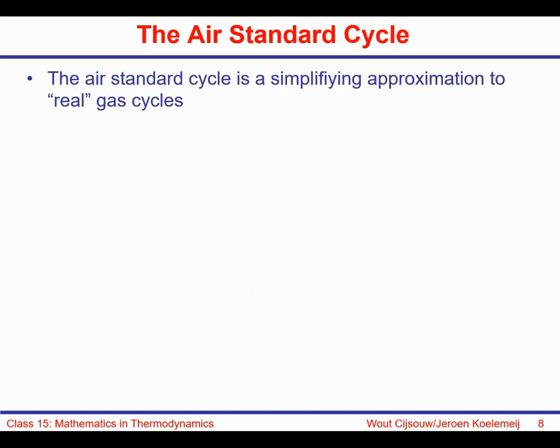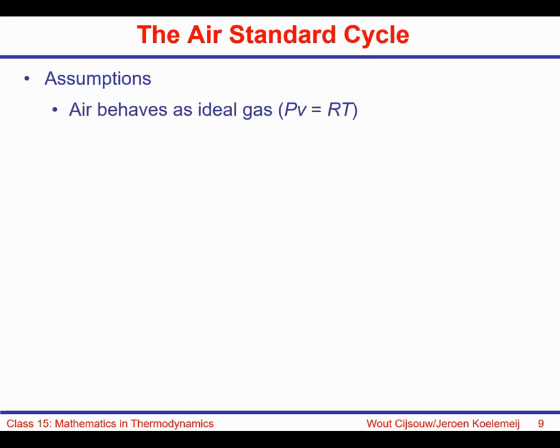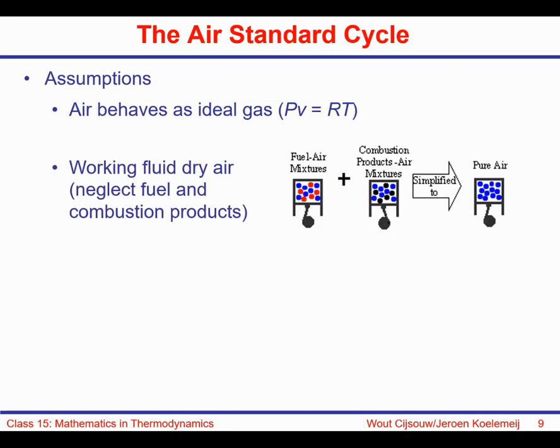Now, there is something that's called the air standard cycle. It's a tool to simplify real gas cycles. So it's an approximation, and it's useful to understand trends or comparing different scenarios in a qualitative way. But it's not so good for a detailed quantitative analysis. And the assumptions that are being made in the air standard cycle approach are that air behaves like an ideal gas.